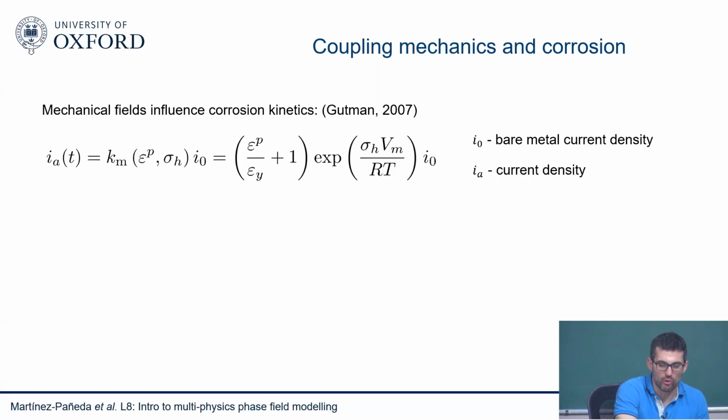And that's important because when you extend the model to account for mechanics, we actually decided to do it in a non-variational form, or in a way where we break down the variational consistency. Because if you do it ensuring variational consistency, then you get non-physical behavior. You get mechanics enhancement in both activation and diffusion control corrosion. So yeah, one has to square the circle now. For the moment, I think the approach we have proposed is the best of both worlds, and the only one that can capture really what happens in the physics.